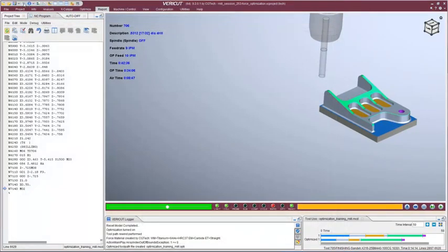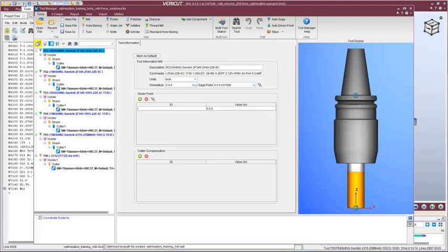We'll look at another report coming out of Tool Manager. If you recall from my earlier comment, each tool has a stock material record used for optimizing this tool and also describing how that tool is supposed to be used. These can be created by the NC programmer, or more frequently they're downloaded with the cutters from places like Machining Cloud, and also tooling databases like Zoller and TDM have the ability to store this information with the tools. We call it tool intelligence.